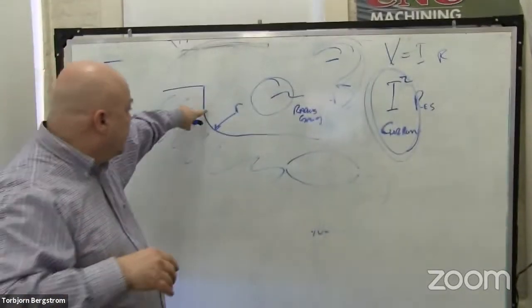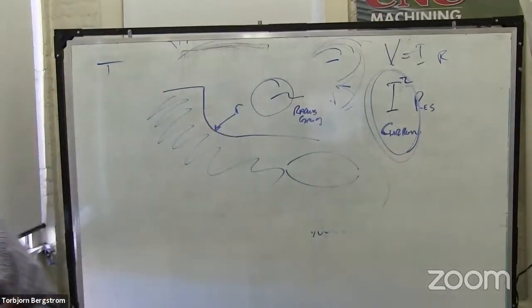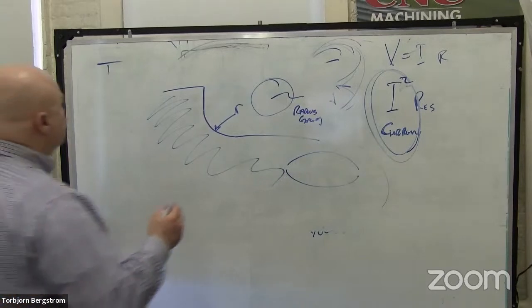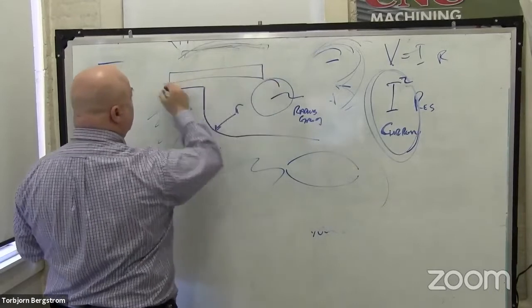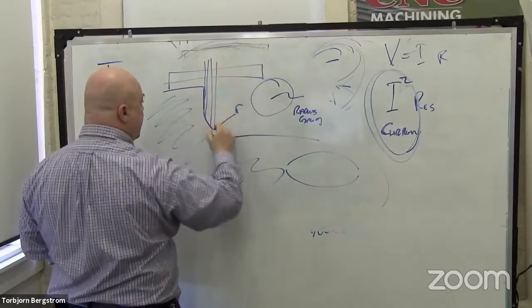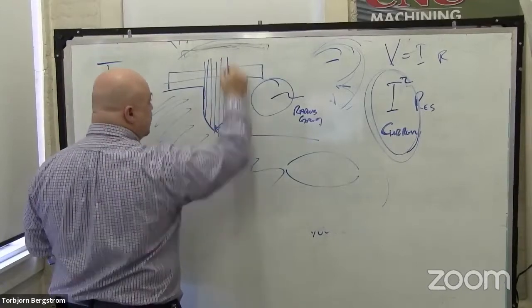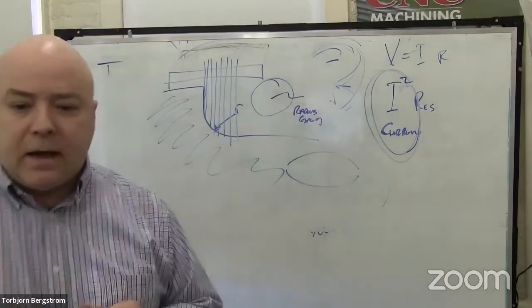How else could I measure this radius if I didn't have a radius gauge? If I had a reference surface that I could cantilever out over here, I could measure the depth at many points, put it on a graph and plot it. I can calculate the radius.